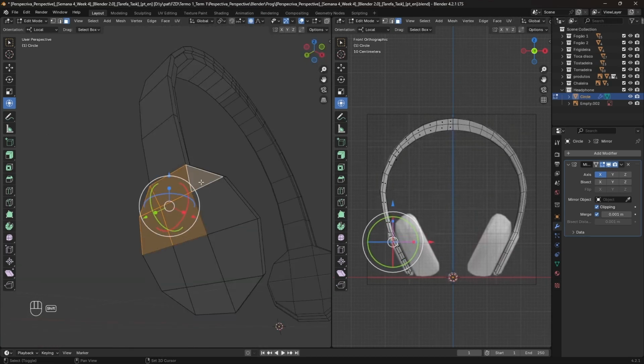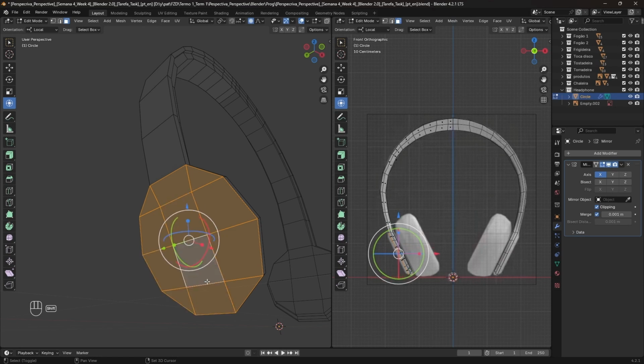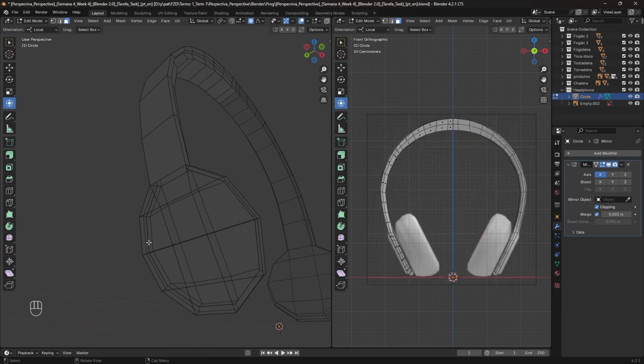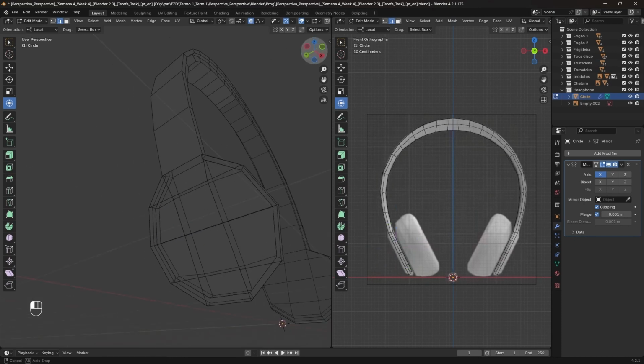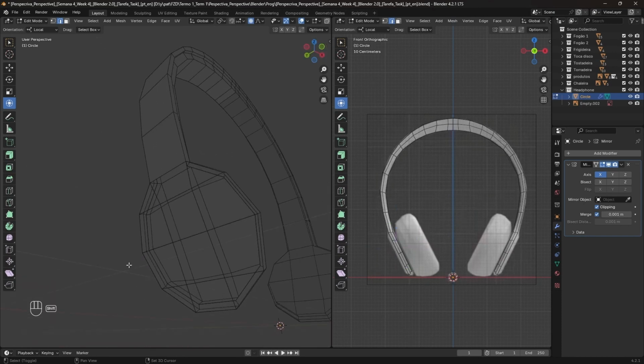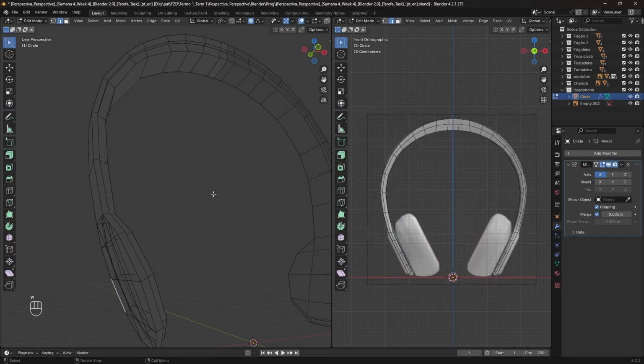duplicated vertices. So what happened over here is that I was trying to extrude, and then I extruded it, but I didn't notice that I extruded. So I ended with one vertex on top of the other vertex. So in this kind of situation, the idea is just to do all the things manually, like trying to delete the duplicated vertices.